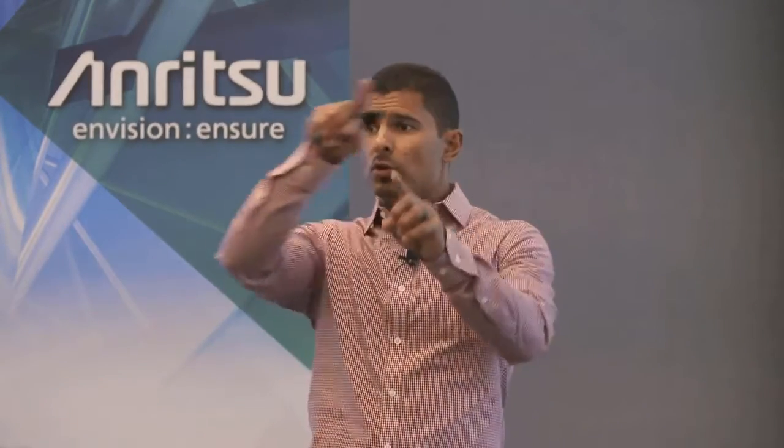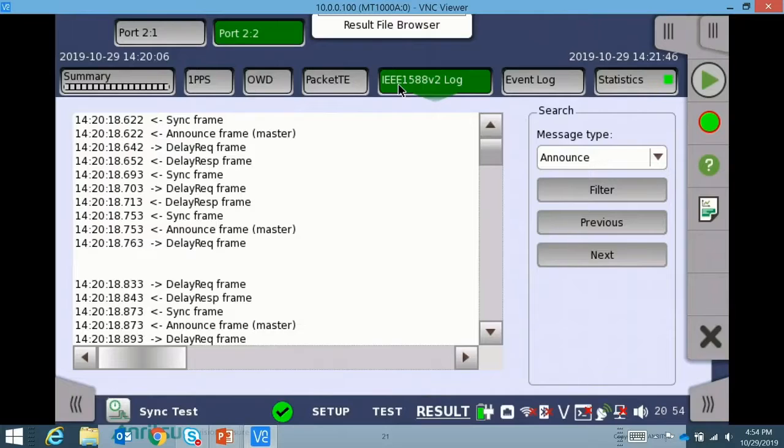Here's basically the messages. Remember in the presentation that I showed, when I was showing the two-way, the T0 to T1, T3 to T4, going back and forth, right? That's what these messages are. These are the messages of the announce frame from the master, the delay request frame, the sync frame. This is the constant communication between the grandmaster and that of a slave clock or a boundary clock. This is what's adjusting the offset for your timing to make sure they're synchronized to one another.